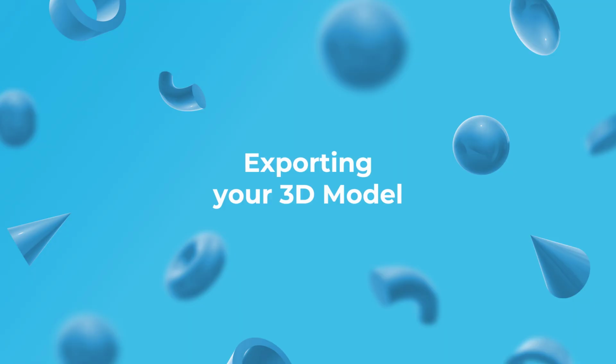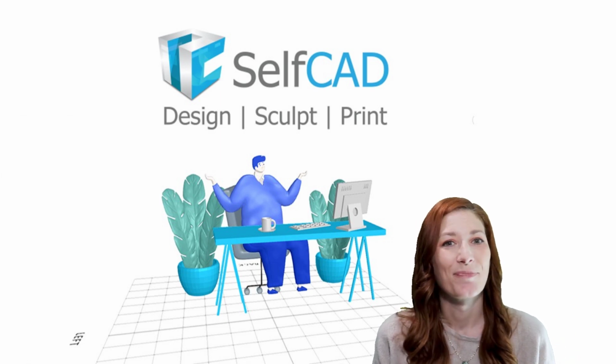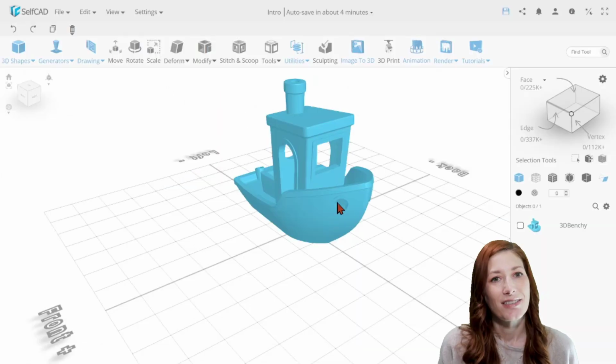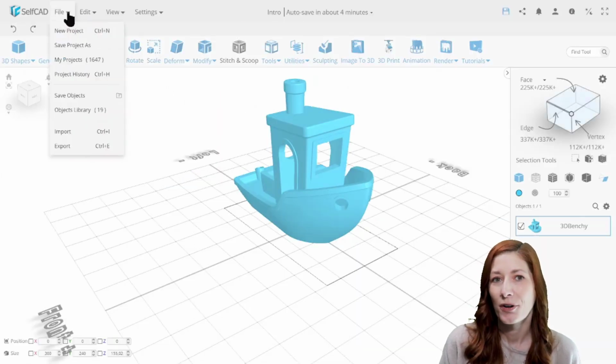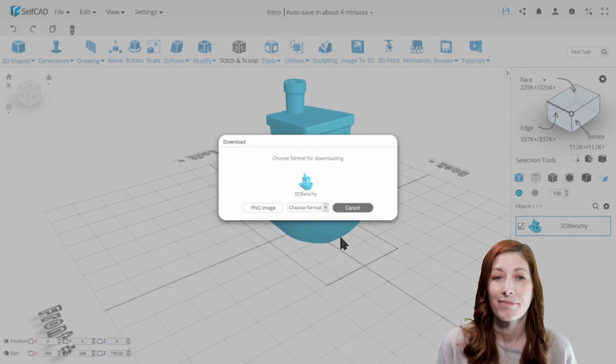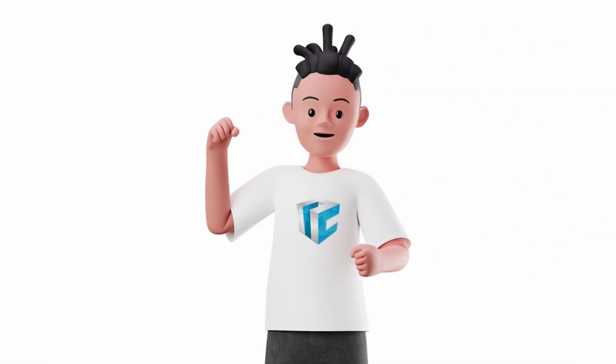Exporting your 3D model. Now that we've finished the object, you might want to export it. In SelfCAD, this process is just as easy as importing. Just click on the File menu at the top left corner of the application, click Export, and select the file format in which you want to save the object. It's that simple. And that's it for this video.